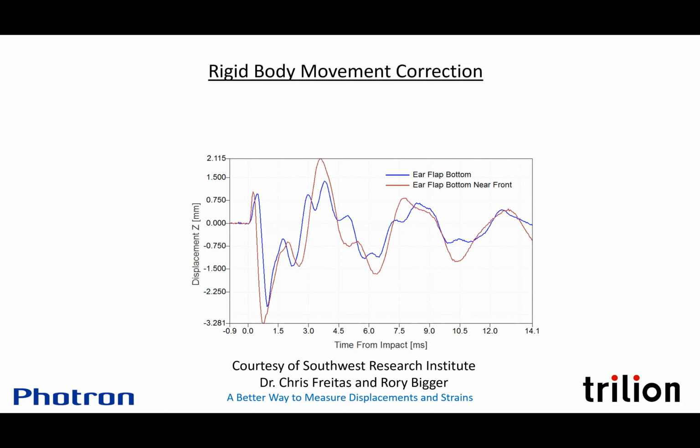Okay, a couple more questions. If you are measuring thermal strains, for instance, can you image in the infrared? Yeah, that's a good question, and there's a couple of interesting answers to that. Yes, there are cameras that are sensitive in the IR, so that can be done. Similarly, at the opposite end of the spectrum, sometimes there's benefits to using UV cameras, especially at high temperature, to help suppress the radiant glow.